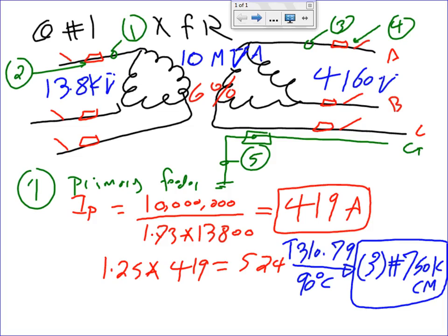3 insulated aluminum cable with 3 conductor cables. So you might have to go single insulated aluminum. 81 says single insulated copper conductor directly buried in earth based on ambient temperature. That could work for us. Or 3 insulated conductor cable, multi-conductor cable, triplex.